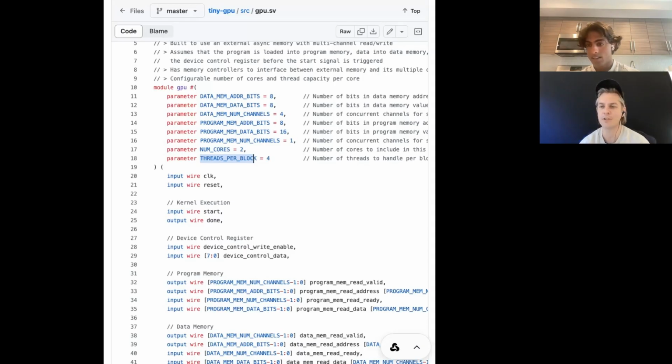And the clock, just to set a foundation on that as well, is essentially an electrical impulse. It's a change in voltage that is getting applied through the whole chip. Is that right? Yep. So the clock is basically a cycle. It's like a sine wave almost, of some signal going from high to low over and over at some periodic interval, usually a couple nanoseconds, like 20 nanoseconds or something like that.